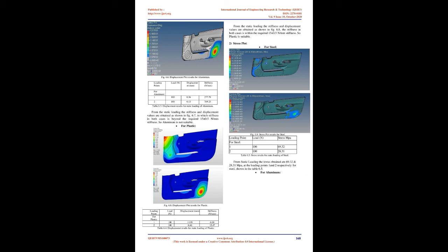By increasing the mass of the door trim, that is by increasing the density, we also provide extra stiffness. Once the mass increases, modal performance also increases and thereby attains the desired natural frequency, 25 Hz. Modal analysis means the goal is to find the natural frequencies, mode shapes, and eigenvectors under free vibration.